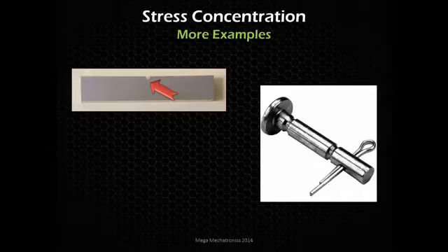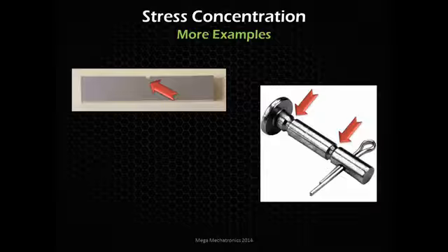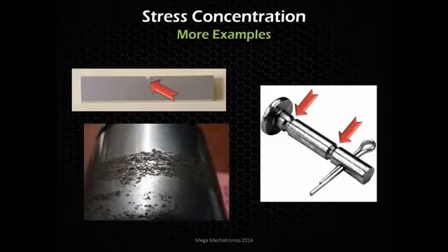And let's look at the shear pin on a snow blower, where you can control how the part fails. If something gets jammed in there at a certain force, this pin will break at these points and give us a predictable and most likely safe way of breaking.